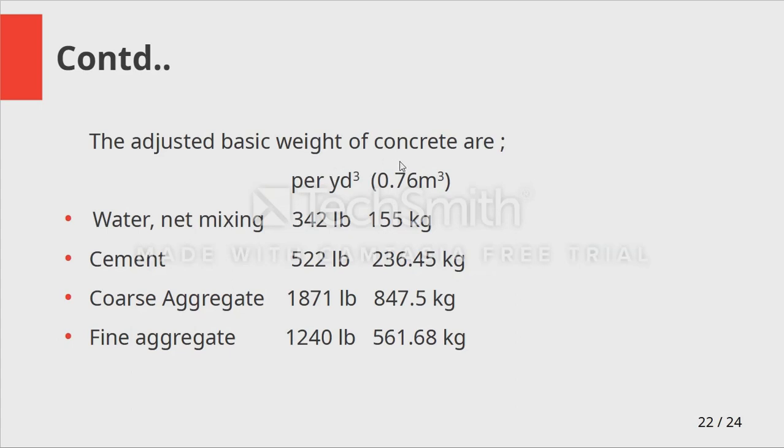Now you have the adjusted basic weights of concrete, so you can multiply these values with any volume that you require. So you will get the quantities that you need to make concrete of desired workability, strength, durability, economy, and all those factors.